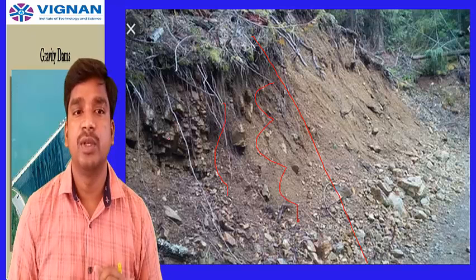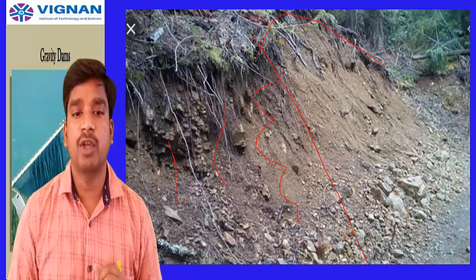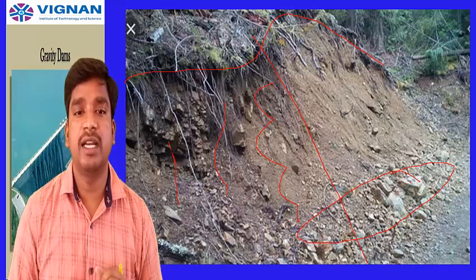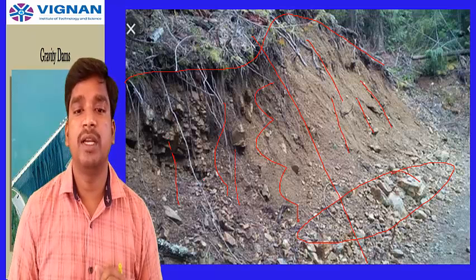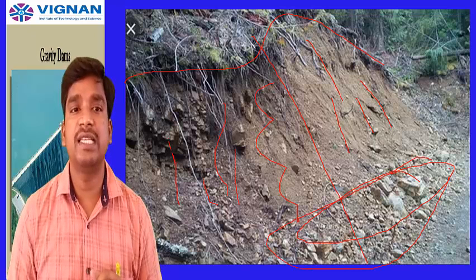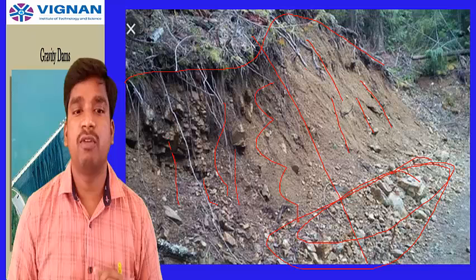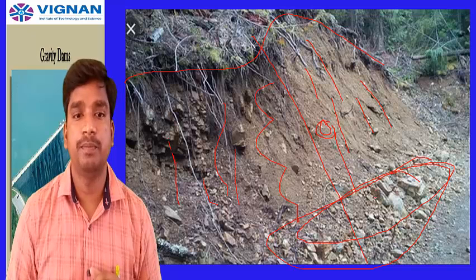It means sliding is occurring. Here you can see this portion is completely sliding and has accumulated here. The sliding is occurring here and the material is forming at the bottom. They are accumulated at this place. So this is called sloughing. Slowly, because of the slope, they will slide and form some slumps, and because of the heaviness of the slumps, they will come down again here. Slowly the thickness of this member may be reduced.